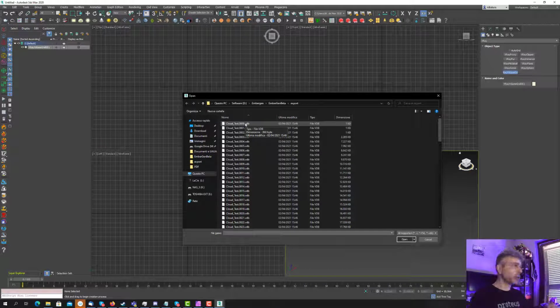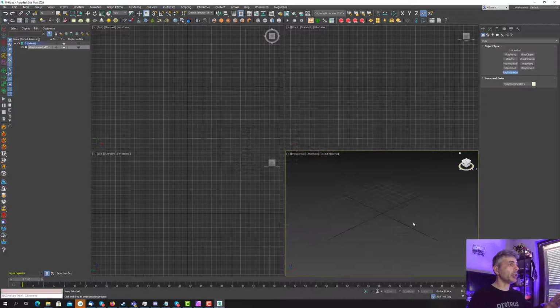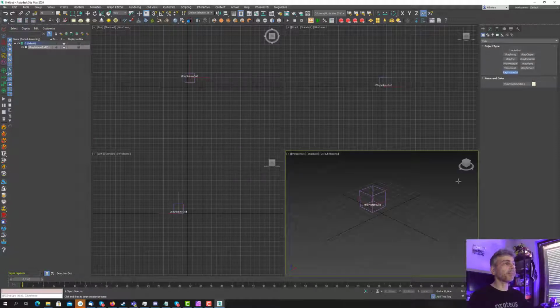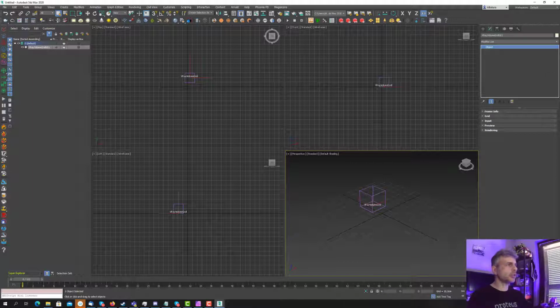So we can use the V-Ray volume object to load our cache. Let's select the first frame. Okay, it is asking for a preset because it can set the volume based on the software that created the volume at the beginning. We have no Embergen preset, so we can say no preset, and we are going to use the manual configuration.